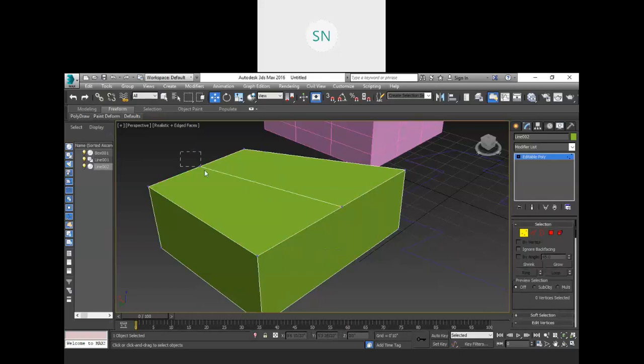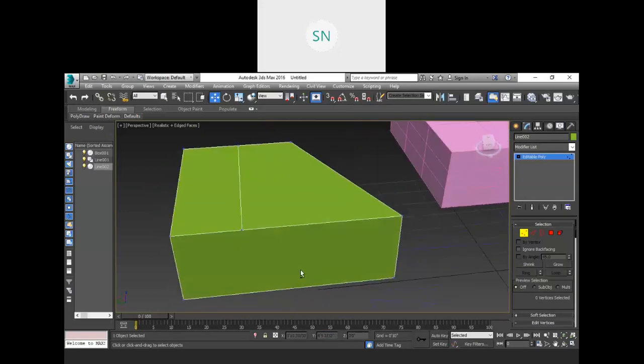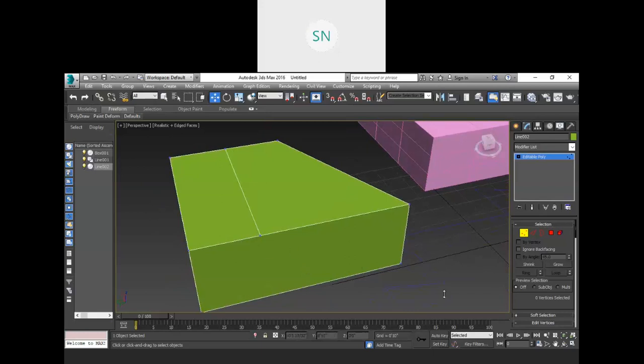Click on the vertices, select this one, check the coordinates, right? We want to focus on the y coordinate, so it's 7 feet 11 inches something, right? You can copy this. Now select the other vertex and paste the position over here. So now these both are in the same position in the y direction. So we have to change the vertices manually. Got it? Okay, good.